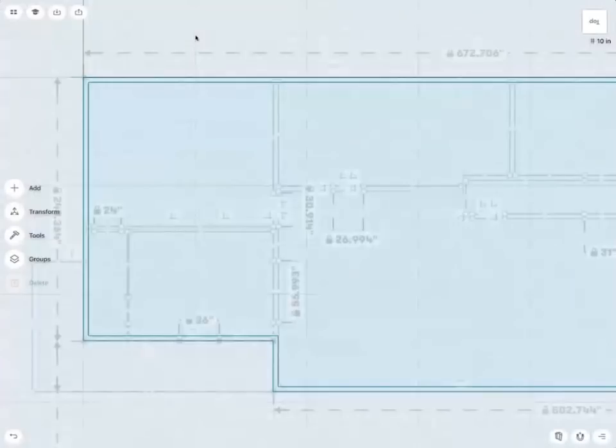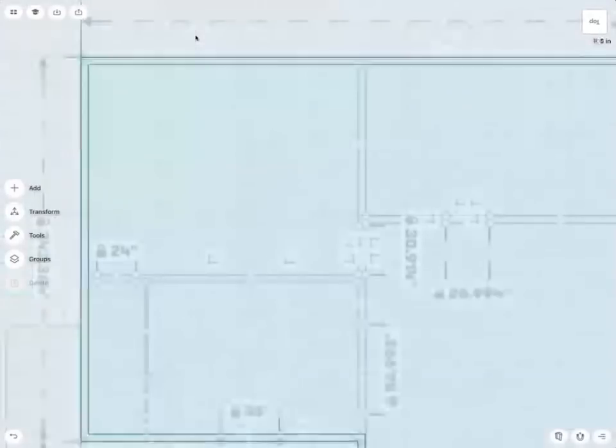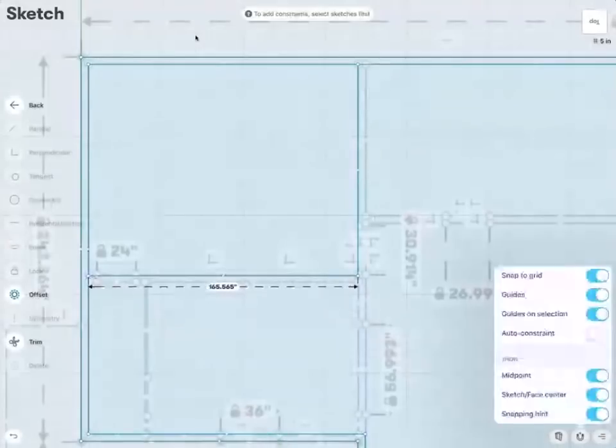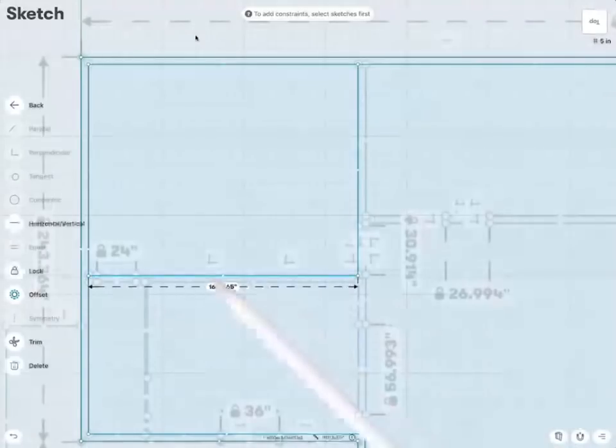Which is now a good point to maybe also talk about how we continue. So the exterior walls we have, we can now see the interior walls. We can easily draw all these lines. So let's say I will start from here to there, draw a line, and from there to there, draw a line. At this point, I might turn auto constraint on if I want to. So I always have the horizontal or vertical elements added. Also here again, very important that this is set.